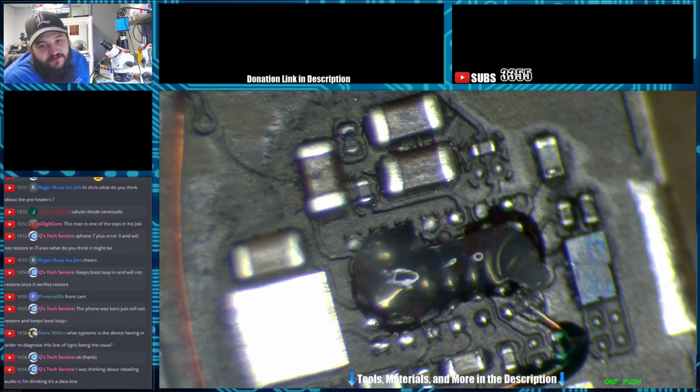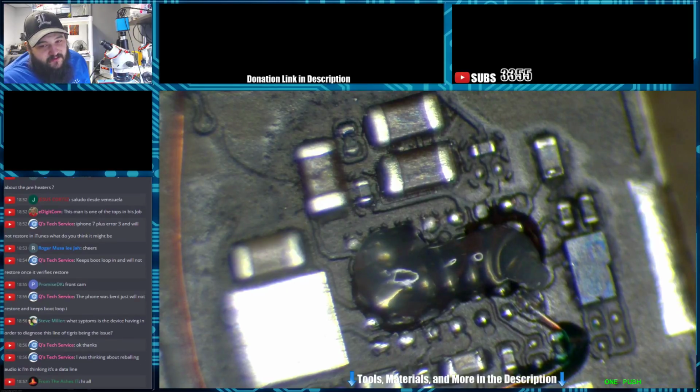When you plug the phone into 3uTools, you pull up the battery data line section. It'll usually say no data, and the battery percentage will probably say 0. When you open up the actual details, it will usually say there are 0 cycles and that the battery has 100 milliamp storage, and that means the phone cannot see the battery itself. So the phone freaks out because it doesn't know if the battery's overheating, or if it's getting too much amperage or too much voltage. That data line is very important for the phone to function properly.